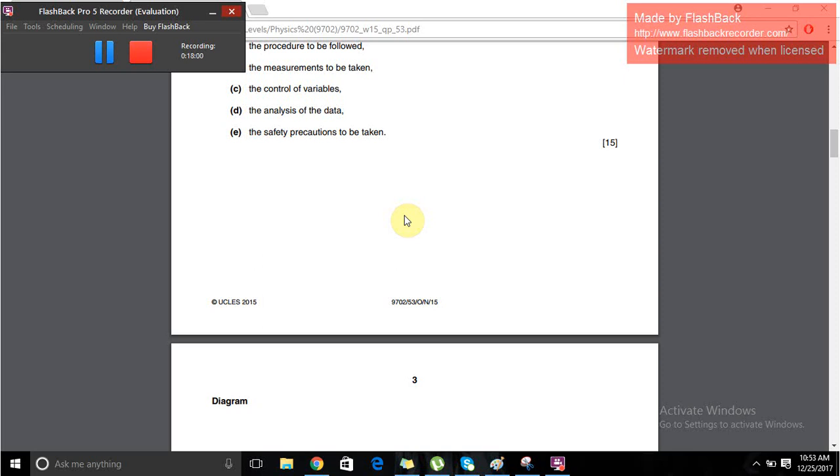And then what do you do? You need to know the value of the power, which is basically V into I, and for that you take the value of V from the voltmeter, which is in parallel to the heater, and the ammeter that is in series with the heater. And you ought to be observing that the values of I and V are constant. They ought to be, right? And to calculate E, E is equal to P into T.